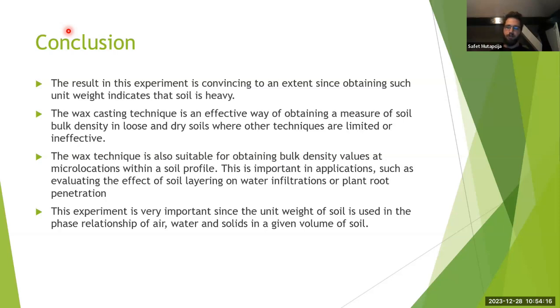So that's the reason why you're going to need CBR, Proctor, those tests like water content, because you're going to change it, unit weight, because it's going to be different. And then you're going to calculate everything on your side based on your laboratory data.